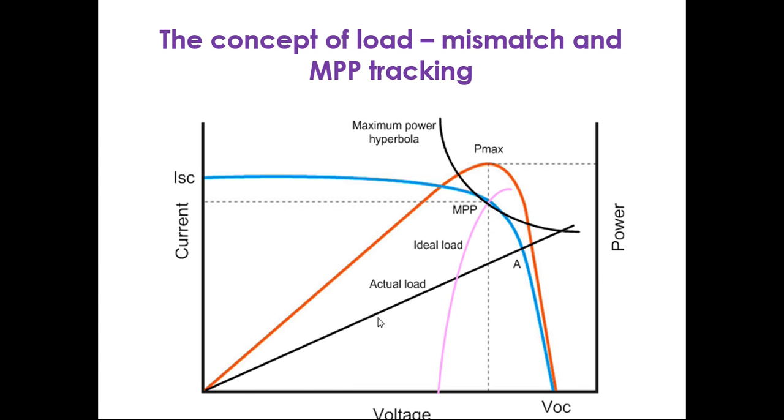Every time your load is going to change. Suppose this actual load is over here, now it might be over here, it might be over here. At that time we can track this power. For that, the maximum power point tracking algorithms are used. See guys, there is no magic in this. We are just playing the impedance matching game.